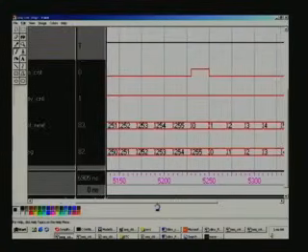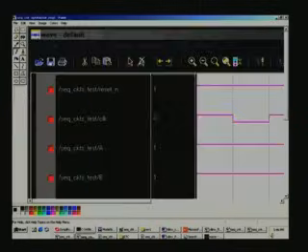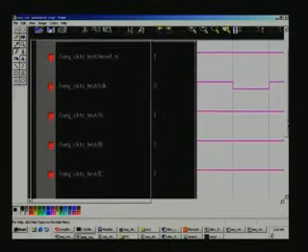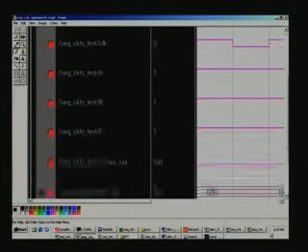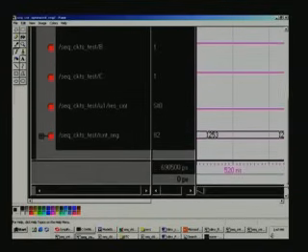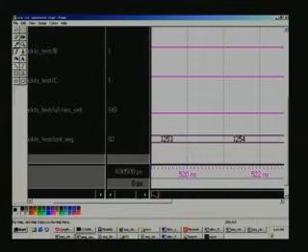Coming to this, it is advancing, this you have already seen earlier, and again it wraps around the counter. The optimized one corresponding to that is this: the clock is here as before, and ABC are all 1 here, so the count is advancing, that is the condition for advancing. From that we can make out, although this advance count is removed in this. And the last one is the count register.